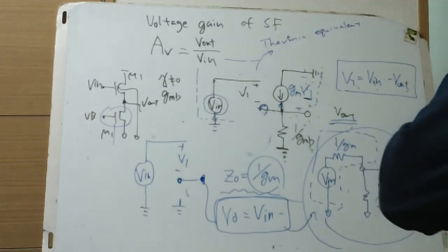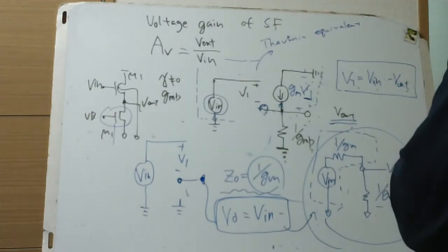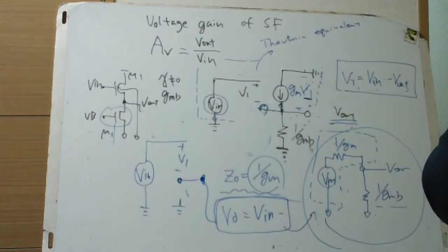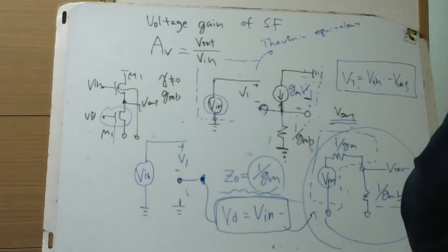So if there are current sources, we need to reject the current sources and equivalently access the controlling voltage, with the independent current sources open, to find the equivalent voltage source for the Thevenin equivalent. I've never read a document or textbook about that kind of procedure, but seemingly it's correct in this case.